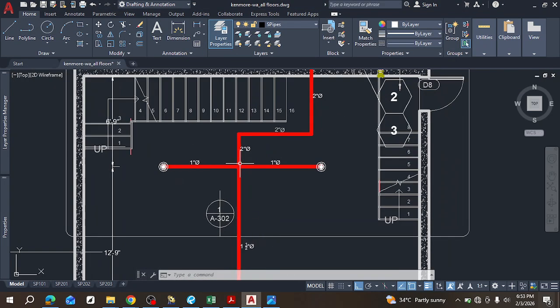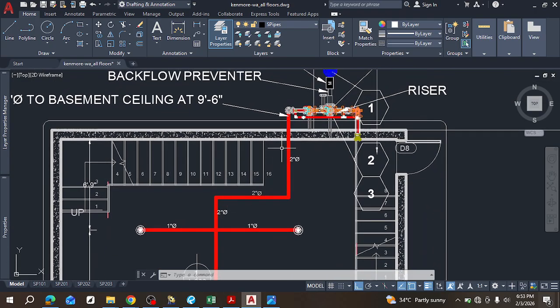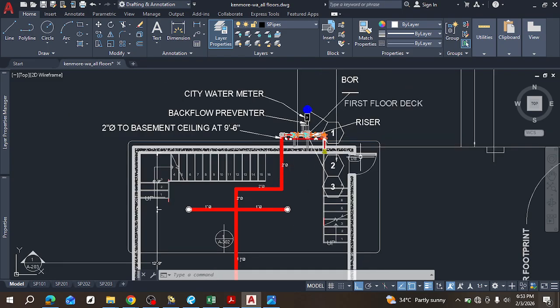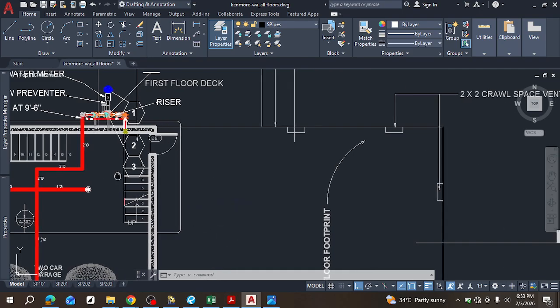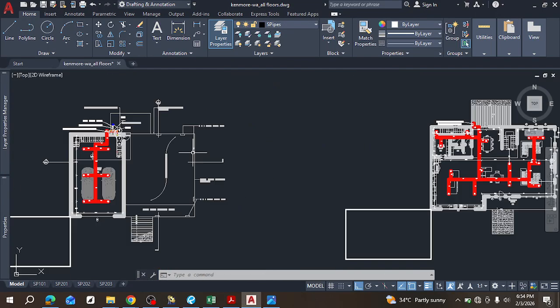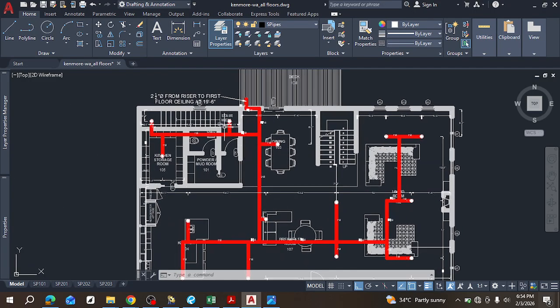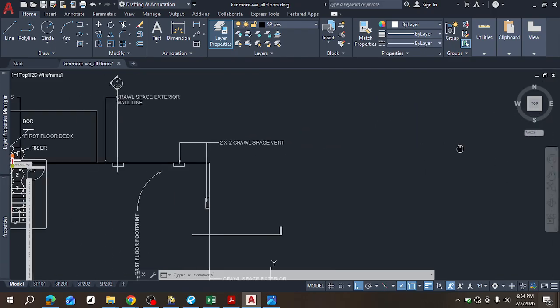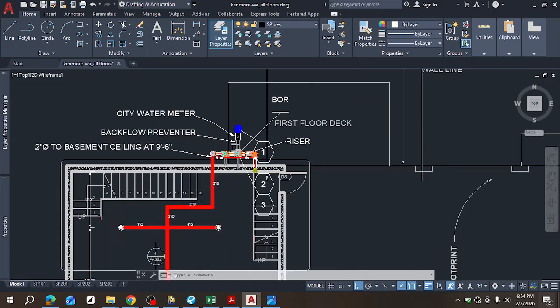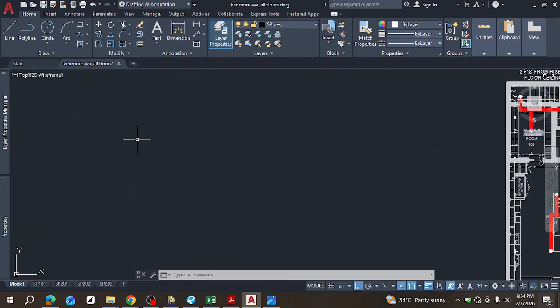So we do that and then keep increasing it accordingly as we move, right? And as it increases, it doesn't increase as fast as that 1, 2, 3, 4. So our largest pipe supplying all 6 of them is 2 inches. Right, so let's go over to the next one, which is this. Now see that riser I spoke about. This is what the riser will look like, and it has like 3 outputs for each of the floors.